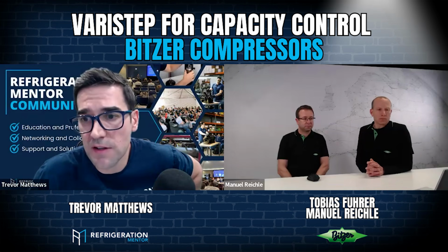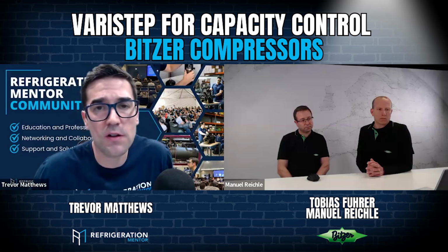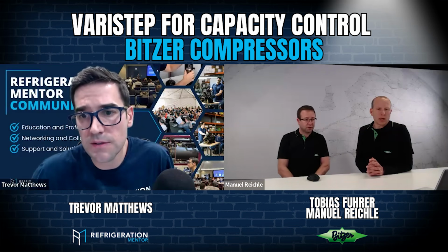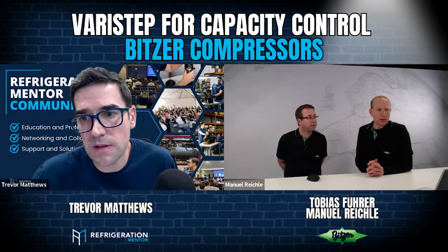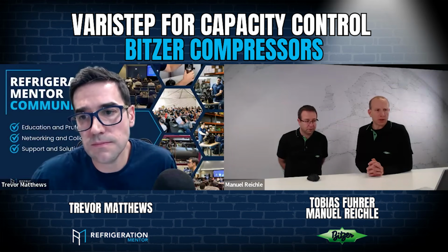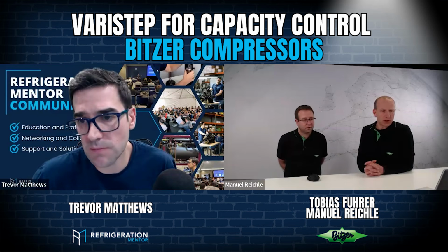Next question: do LSP motors need a speed drive? Well, I think earlier you said you have Varistep with LSP motors, right? LSPM, line start permanent magnet motors. They can use a frequency inverter, but they don't have to. They can also run, for 60 volts, 60 hertz direct online.